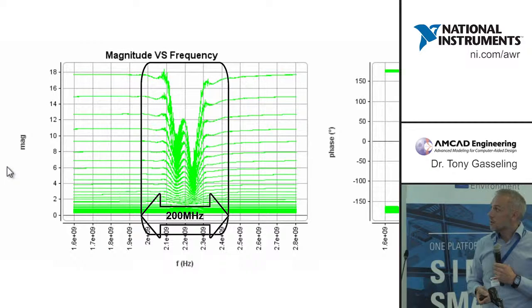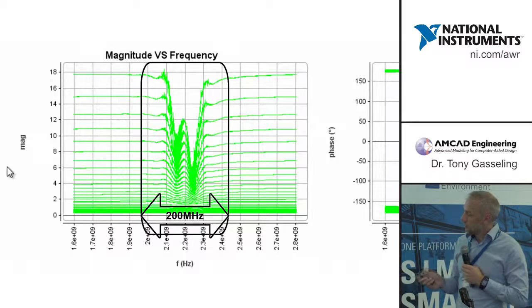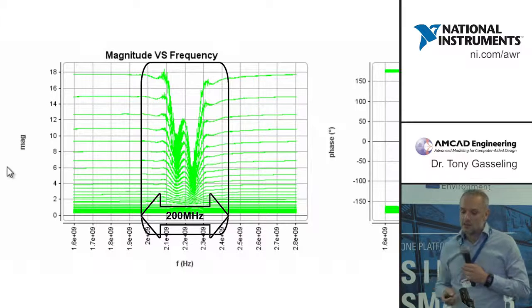And we will observe the behavior of this low frequency memory effect that takes place at low frequency. For example, here we can observe that the main influence is in the 200 megahertz bandwidth. That is to say, there's no need to take all this data into account in the model, because it will increase the weight of the model without bringing any benefits.